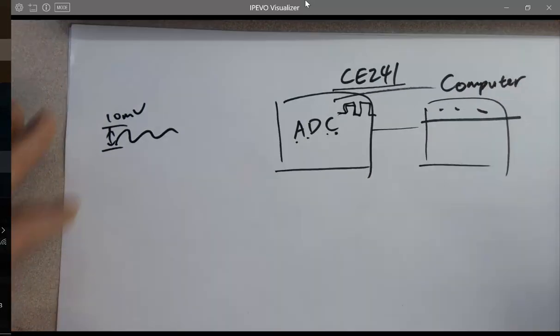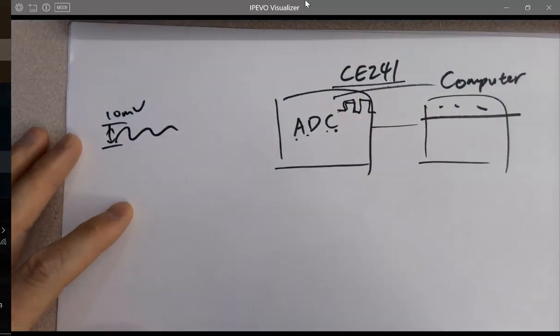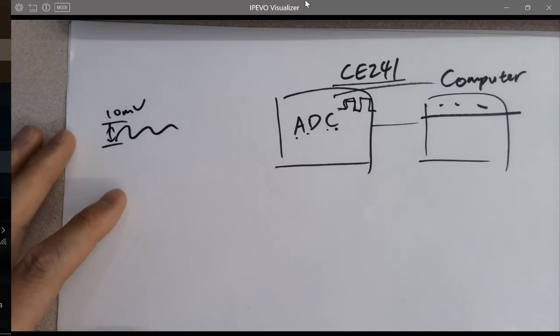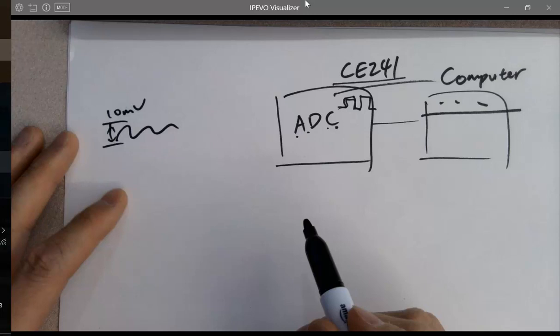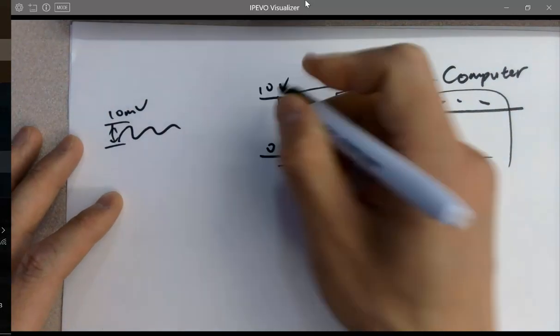That's how that works, because we eventually need a computer to process everything, and the computer only stores digital data, like ones and zeros. So how do you convert whatever temperature into ones and zeros? You need an ADC. Analog to digital converter. You need the ADC to convert the signal to digital, but this one has a range, usually 10 volts to 0 volts.